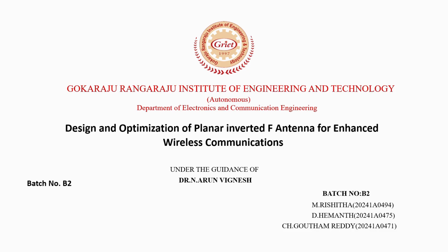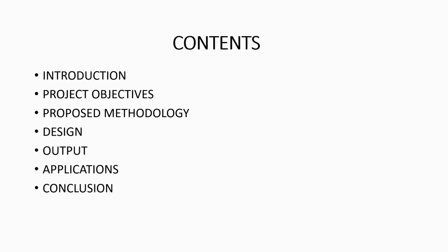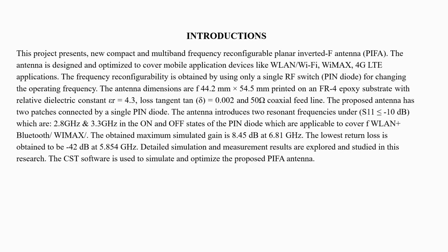Coming to the contents of the presentation, the contents are introduction, project objectives, proposed methodology, design of the antenna, output, applications, conclusion. The introduction: the project focuses on enhancing a planar inverted F antenna by integrating a single PIN diode for frequency tuning through rigorous electromagnetic simulations and optimization techniques. The goal is to precisely manipulate the diode's biasing to dynamically adjust the antenna's resonant frequencies.